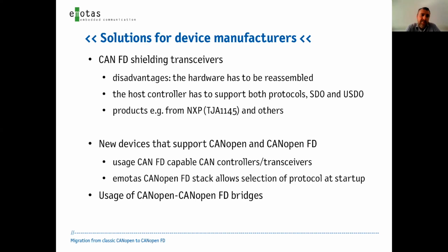But using such CAN FD shielding transceivers, you can build devices which work as classical CANopen devices, but can be used in a CAN FD or CANopen FD network. But there's another problem. The host controller has to support both protocols, classical CANopen and CANopen FD, and also the SDO and USDO service for both protocols.